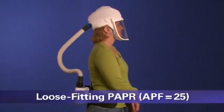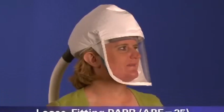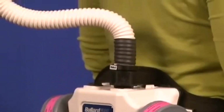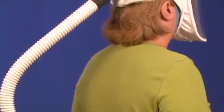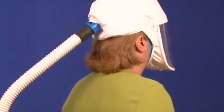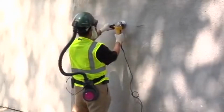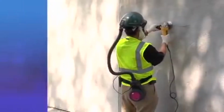This is a loose-fitting facepiece powered air-purifying respirator, or PAPR. A PAPR has a blower that pulls air through attached filters. The blower then pushes the filtered air into the facepiece, which covers all of the user's face. Since it is loose-fitting, it does not need to be fit-tested and can be used by workers with facial hair.